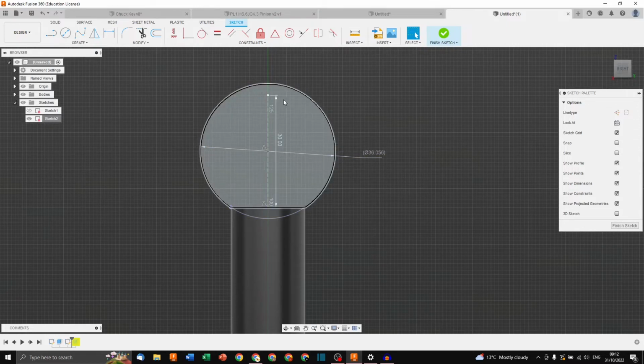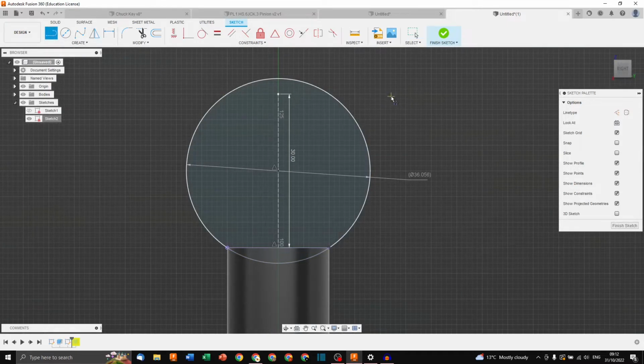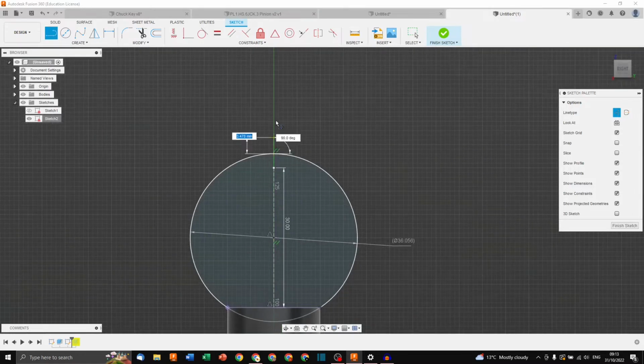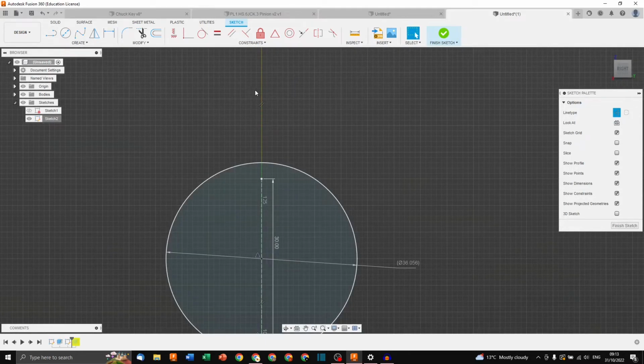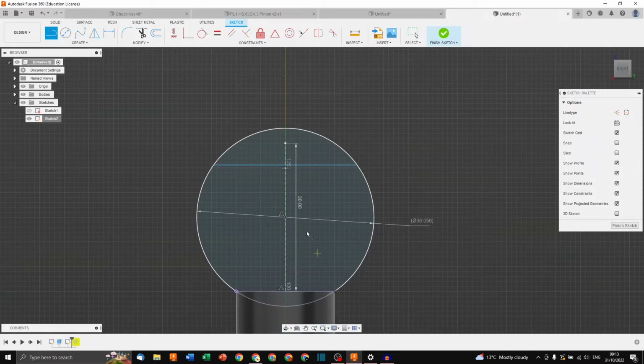So once again, we'd like to cut off the top 45-degree part of the circle. So let's do that cleanly this time. Now, let's go from the top of the circle right here and go back to construction line mode. And let's pull a line all the way up, far, far, far. Great. Now, we'd like a line that starts on this line right here and that is actually tangent to this circle and creates a 45-degree line with this line. We'll take a line, once again, in construction, because we do not extrude this. All that we need to be in full lines, so not construction, is this line, so that we can extrude just the surface into a volume.